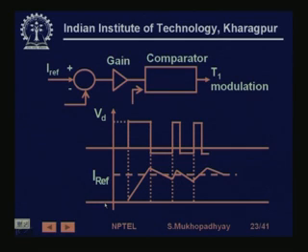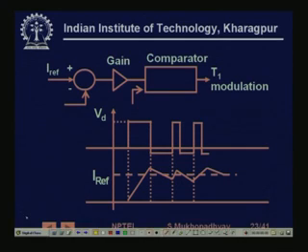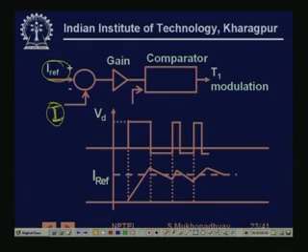So, this is the current I. You do not want the current to increase by more than I, right. This is your reference current where you want to maintain the current in a phase. This is the actual current. Whenever you switch it on, the current starts to build up. Whenever you switch it off, the current starts to fall. So the actual current in the winding is always increasing or decreasing. When you switch on the winding voltage, the current starts building, and then when it crosses a certain limit, you switch off one of the switches.